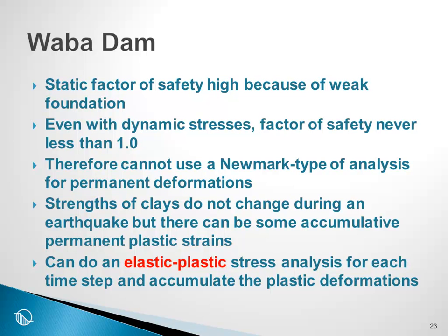So as I've already said, the static factor of safety was very high because of the weak foundation. And if we do a Newmark type of analysis, even with the dynamic stresses, the factor of safety never falls below 1. Therefore, we cannot use a Newmark type of analysis for permanent deformations in a case like this. The strengths of the clays do not change during any earthquake, but there can be some accumulative permanent plastic strains.